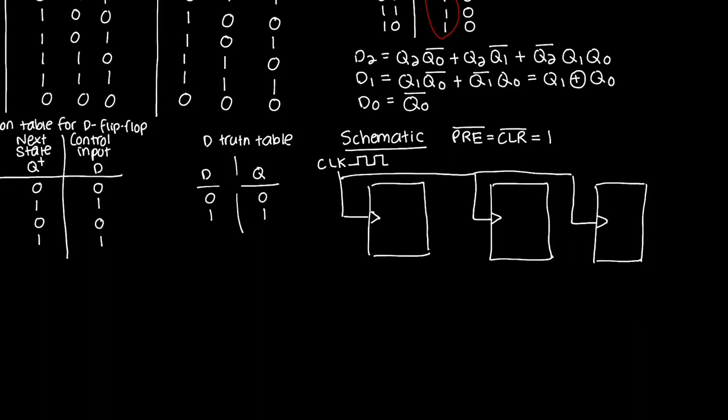And why did I do that? I just did that because it was easier to wire. But I don't have that problem here with synchronous counters. So I'm going to go ahead and restore rightness to the universe, and I am going to put the flip-flop corresponding to the most significant bit on the left. LSB goes back to its place all the way on the right.